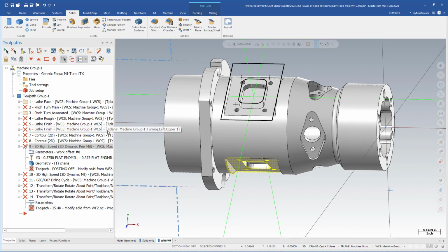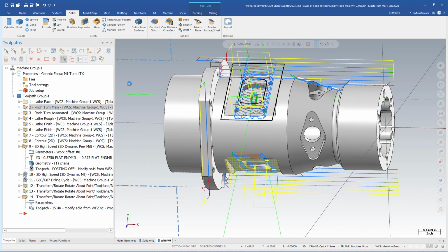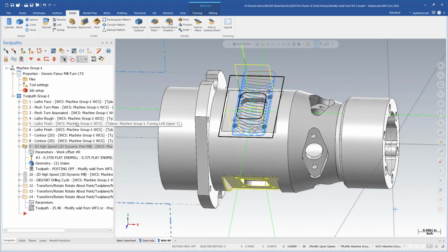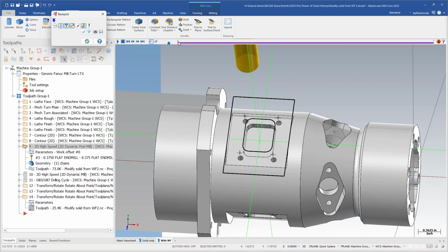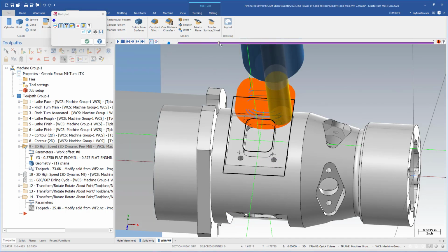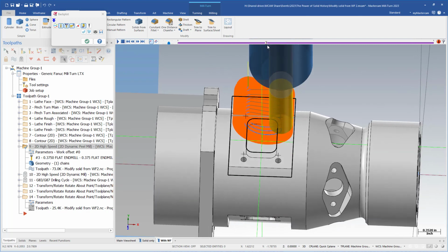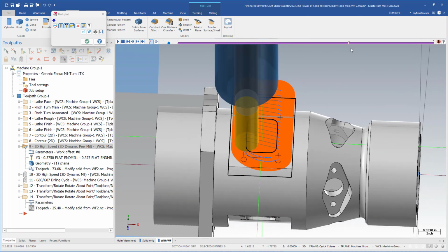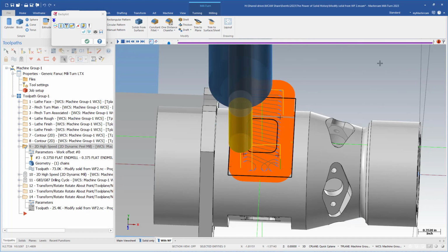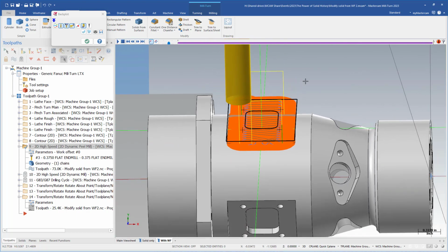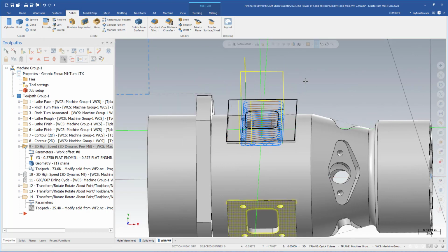The toolpaths also went dirty because I changed the model. But I can hit regen here, and all of the toolpaths have been updated. If we take a look at the original toolpath, which was number 9, I can unghost it for a moment. We can see that the new version of the toolpath, because it's tied to the solid, is already compensated for the new solid geometry. It's going to come back and do a finish pass here. That's why I didn't get to the edges. So that makes it really easy for us to modify our toolpath just based on changing the solid history.